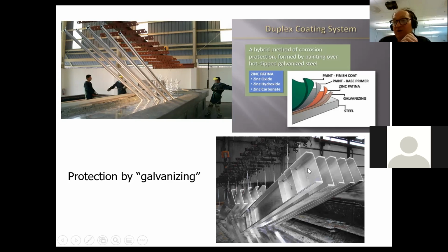And when you pull it out, you won't see any of the underlying steel at all. All of it, or 100% of it, will be coated. So this then can go into service life. It doesn't necessarily need to be painted, it should be pointed out. Sometimes we do and sometimes we don't. Most of the time, galvanized objects are not painted.